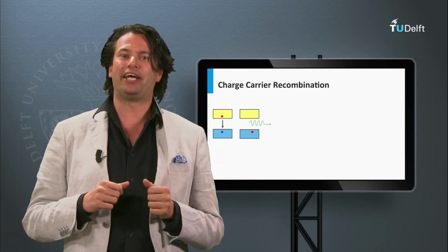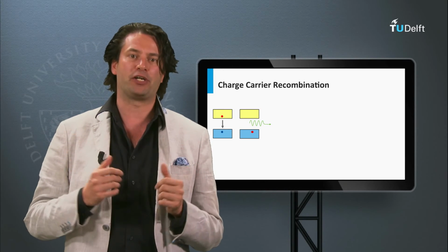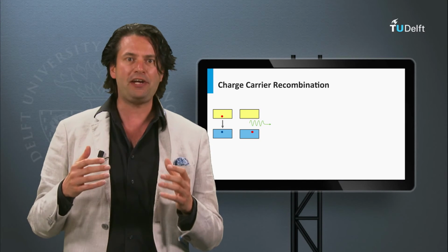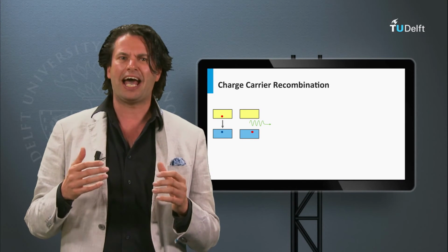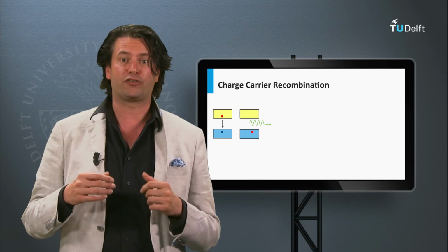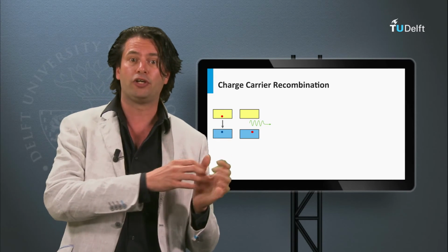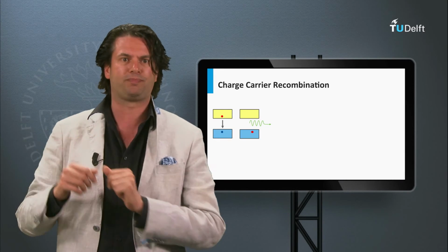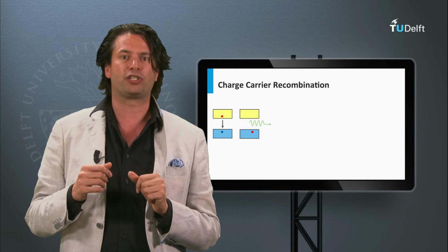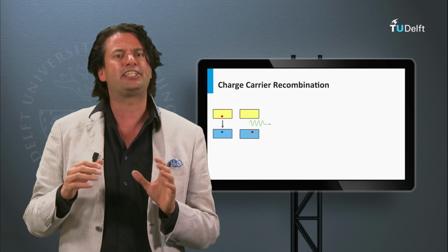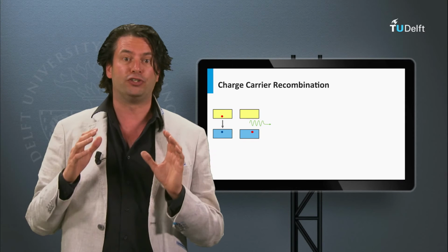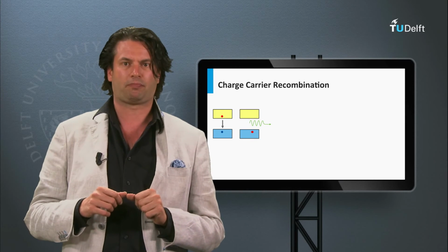The last recombination mechanism is radiative recombination. In the three recombination mechanisms, energy and momentum are transferred from charge carriers to phonons or photons. The efficiency of these processes depends on the nature of the band gap of the semiconductor material used.